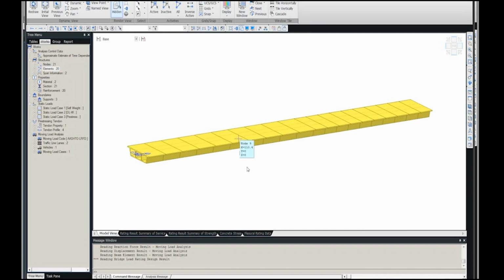And also you can define your permit vehicle. You can perform the load rating on top of this bridge, and complete the result. And also at the end you can get the report. The dynamic report generator can completely create a report for you for all parts, from the modeling, the section property, material property, geometry, everything that you want, and also the results, like checking the bending moments.